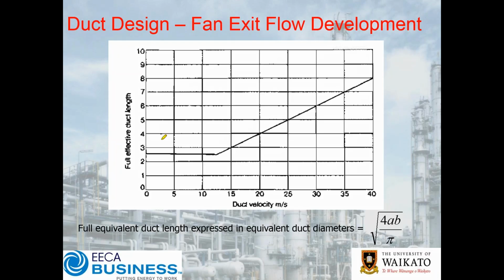So if I just highlight this point, if you're at 10 meters a second, you can probably get away with 2.5 duct diameters. If you're out at 30 meters a second, you're now at 6 duct diameters. So you can see that the faster the airflow, the more duct you need, which kind of makes sense.